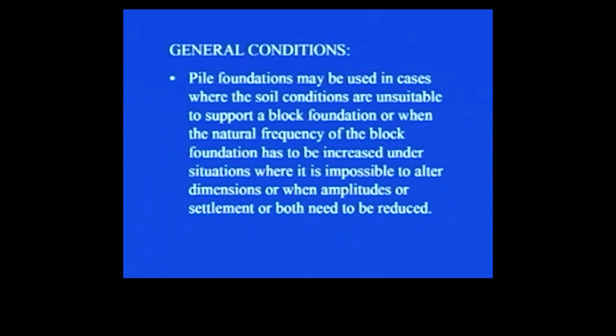Pile foundations may be used in cases where the soil conditions are unsuitable to support a block foundation, or when the natural frequency of the block foundation has to be increased under situations where it is impossible to alter the dimension, or when amplitudes of settlement are both needed to be reduced. As you know, the pile foundation is a type of deep foundation.